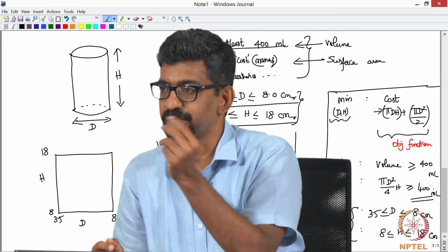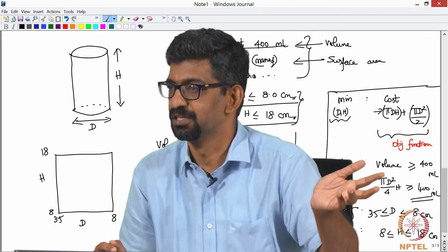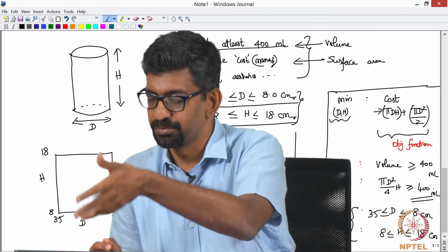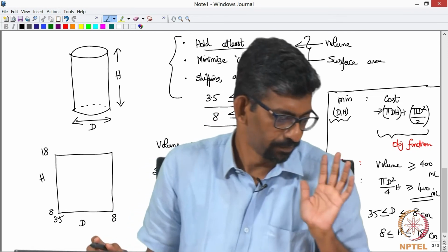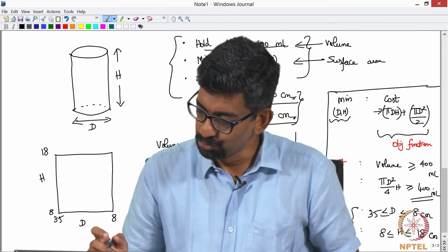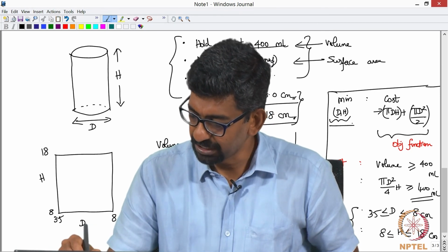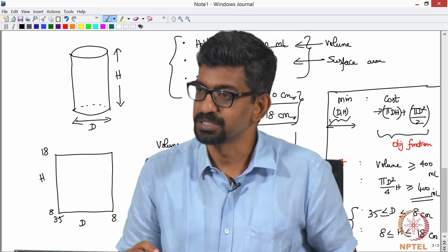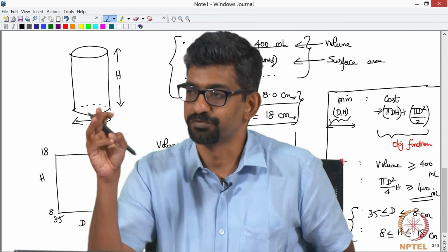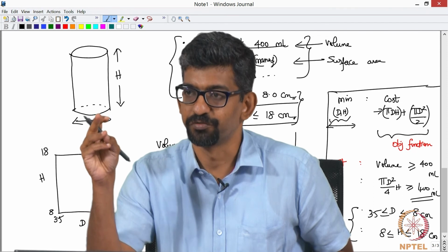For x1 it might be very sensitive, for x5 it might not be that sensitive, but still it is sensitive. So, y is a dependent variable and the x's are independent variables, and your design variables are your independent variables. People are very careful with the design variables because they define the dimension of your problem, the degrees of freedom of your problem.